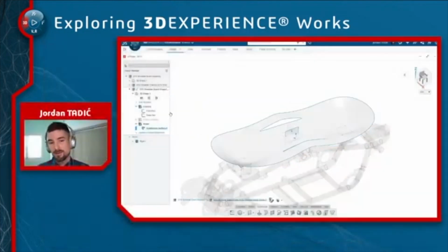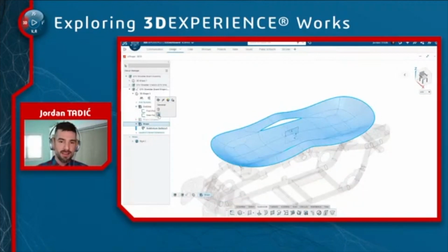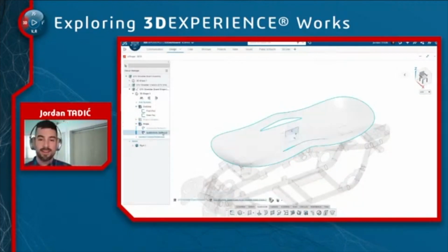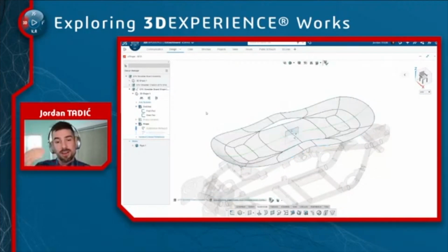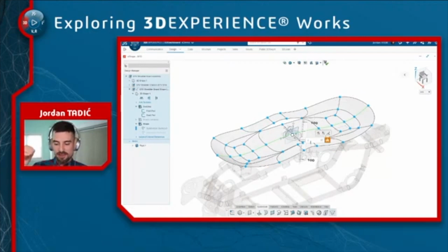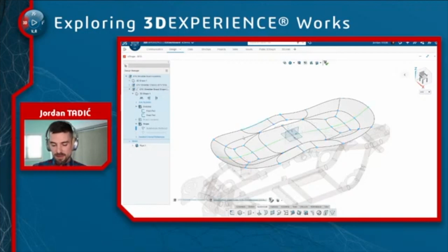Anyways, what I'm going to do here is something a little different, because I don't want this to be a uniform thickness. I actually want the bottom to be a different shape because remember, we have to mount to the mounting pads on the actual assembly. So I'm going to copy that original sub-D body and paste it to make a duplicate copy. I'll hide the original one and then edit the second one. I need this to be down, like a thicken command, about 7.5 millimeters, so I'm going to move that down in the negative 7.5 millimeter direction.